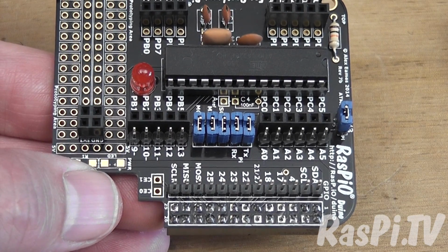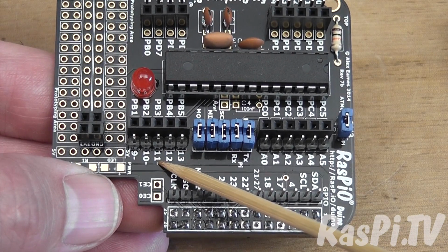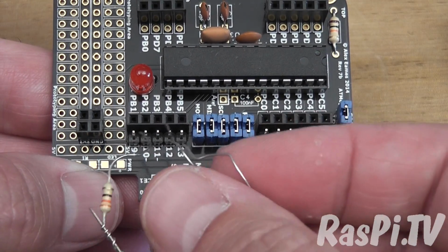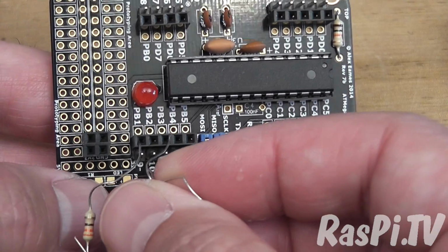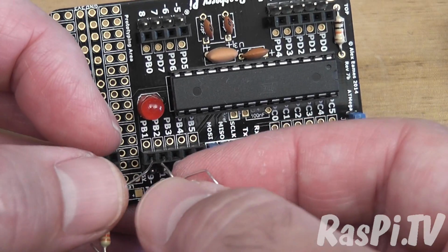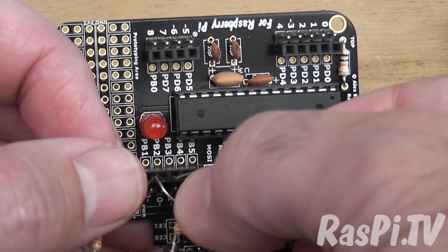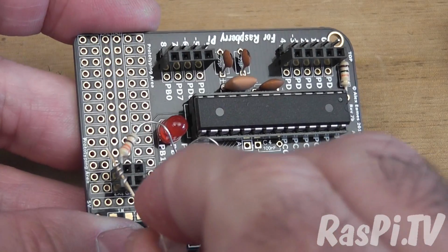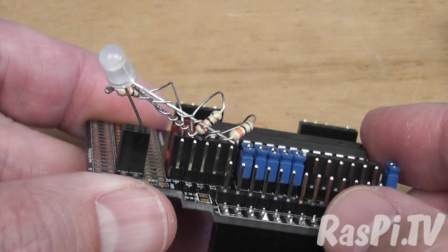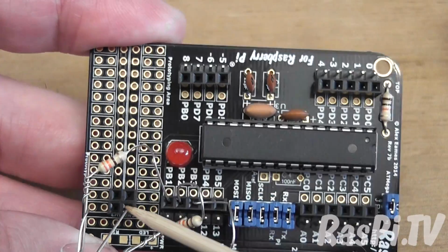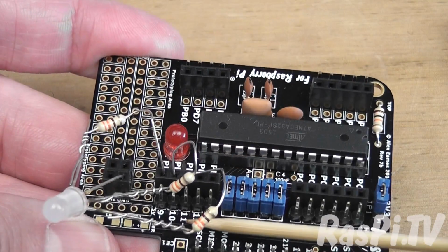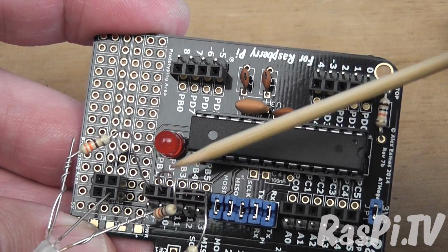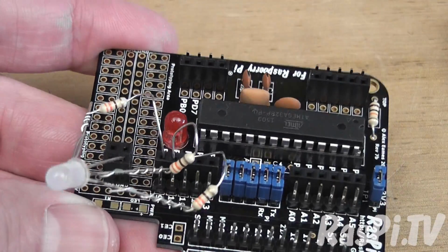So then we're going to connect our resistors so that blue is connected to 11, green is connected to 10 and red is connected to 9. And you also have to make it so that the ground leg of the LED is connected to ground. This is the ground rail here, and there's a socket just there. So we've got blue on 11, green on 10, and red on 9, and you must make sure that none of these wires are touching each other. That's why it's all spread out so much and looks a bit silly.